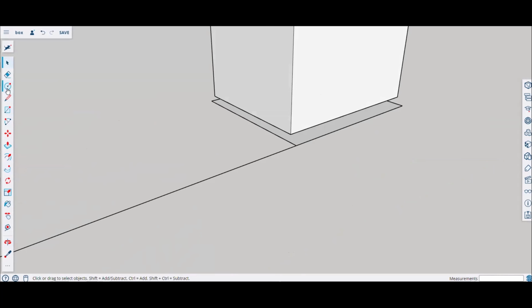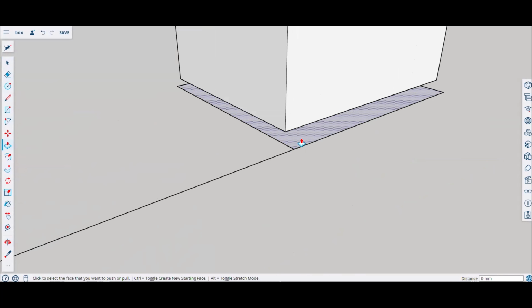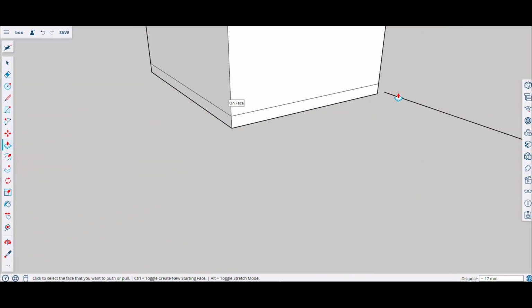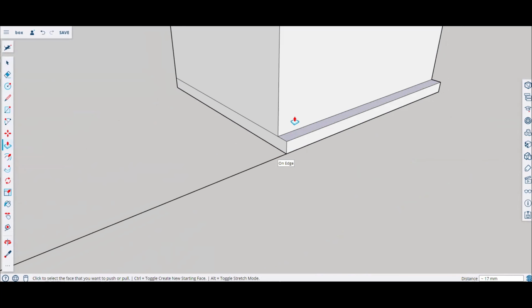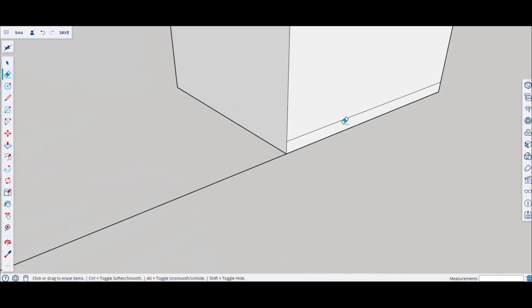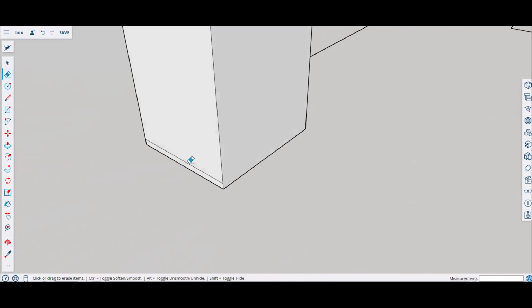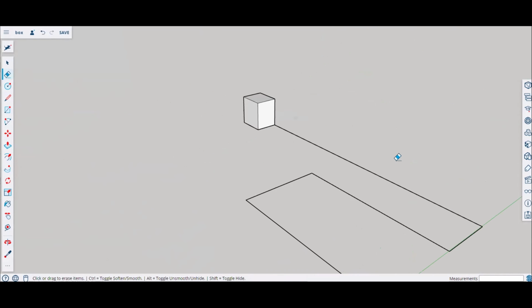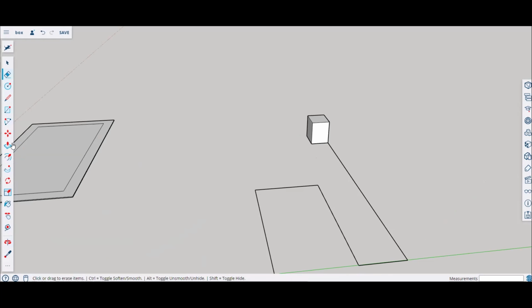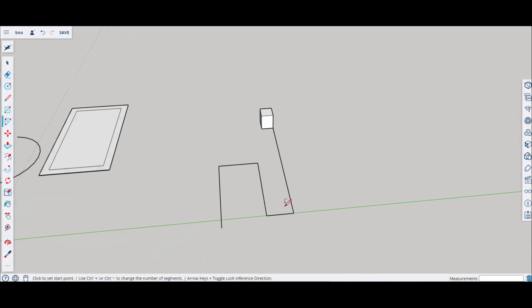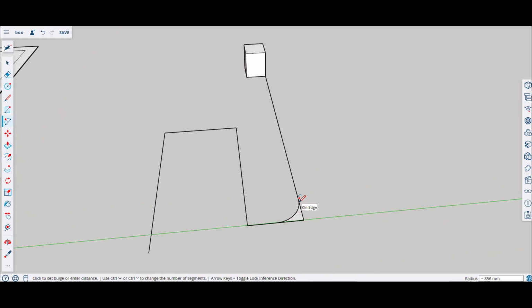And what you want to make sure too, is that this here is all one, and touching the line. This is just showing an example of what Follow Me does. So you can do any type of profile for this particular tool. If you're designing a port and you wanted to do a curve, you can then use the arc tool to create these curves that you want.